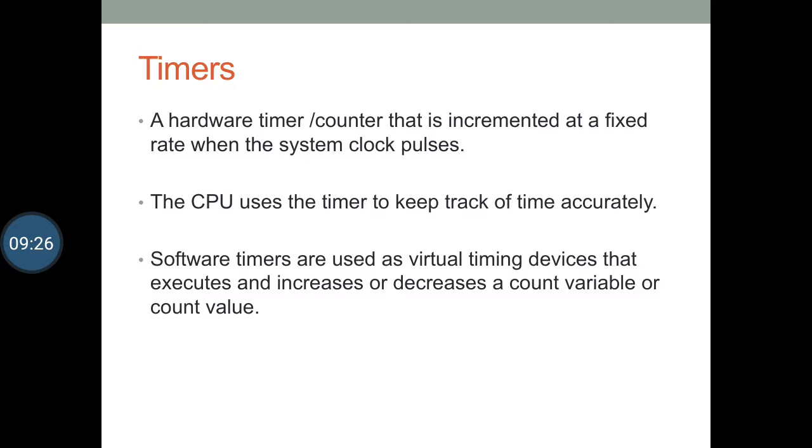At least one hardware timer device is a must in a system, which is used as system clock. The hardware timer gets the input from a clock out signal from processor and activates the system clock as per the number of ticks present at the hardware timer. The number of hardware timers present is generally limited.